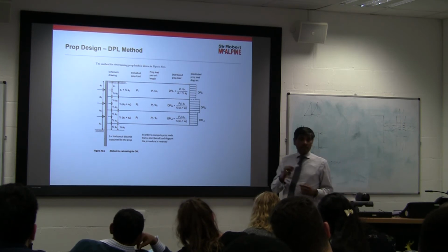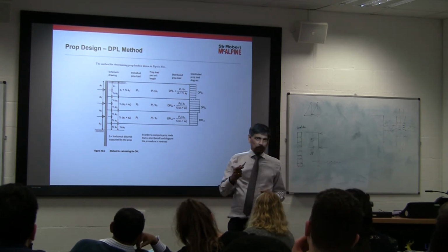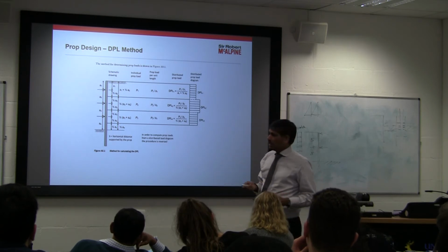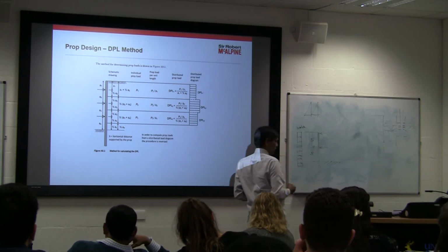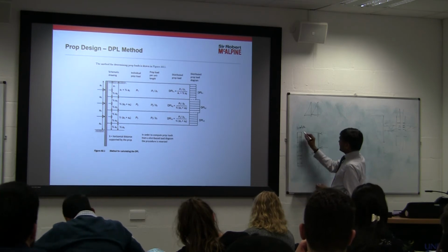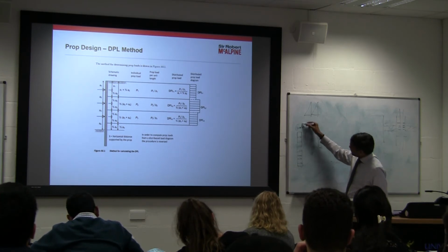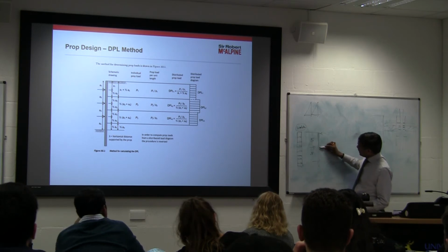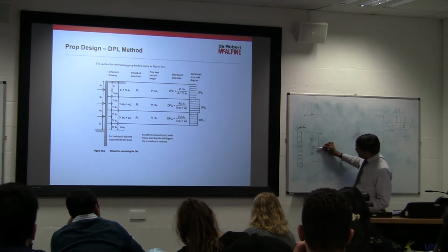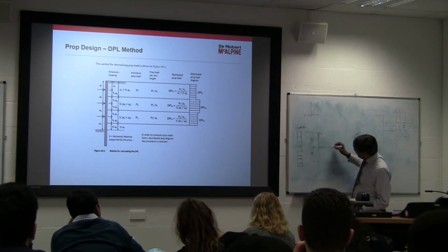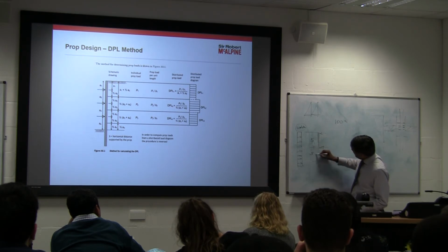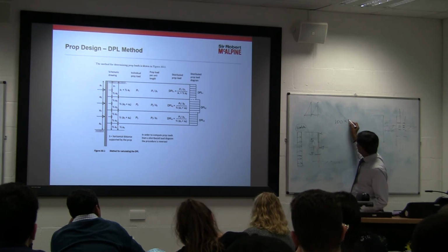Why I have used a rectangular rather than a triangular one? Normally, the Rankine scheme is all about triangular pressure distribution. Same thing with the hydrostatic. But I will tell you about why I have used a rectangular one. If you take a simplistic approach of 100 kilopascals, what is the load on this prop? The distributed load on this prop will be 100 times the prop area, that much here, times 5.